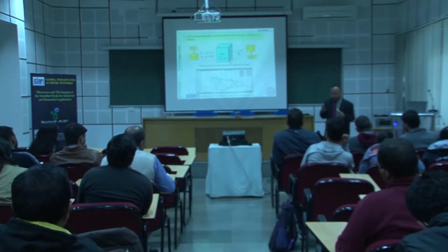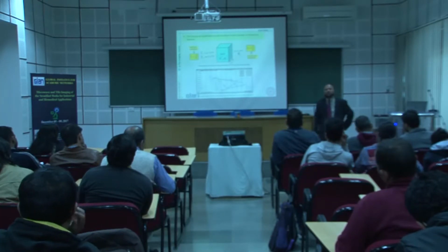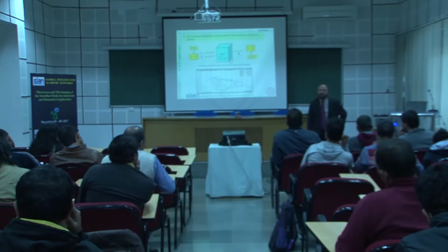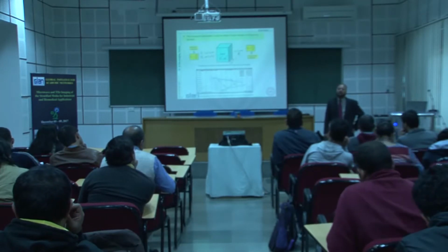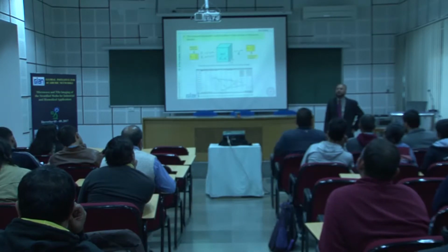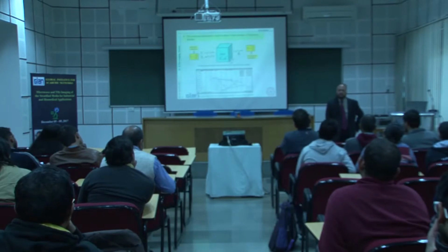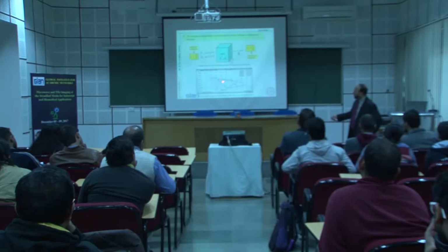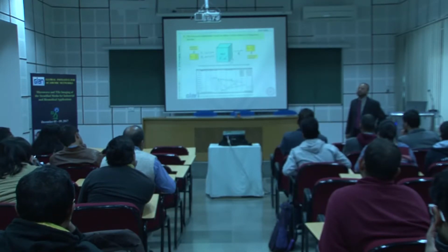And so the idea is that nowadays, without using an explicit time domain spectrometer, if you have a network analyzer which works over a wideband and a wideband antenna, it can equally be applied, because you simply take the IFFT and achieve time domain data, and you can get something like this. And time domain measurement has many advantages compared to frequency domain, because time domain is a real domain.